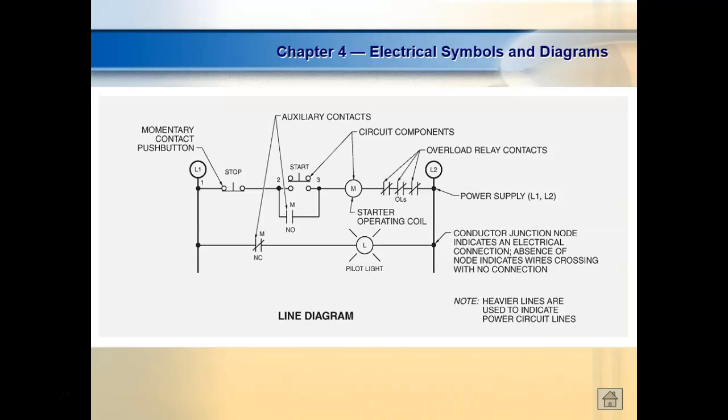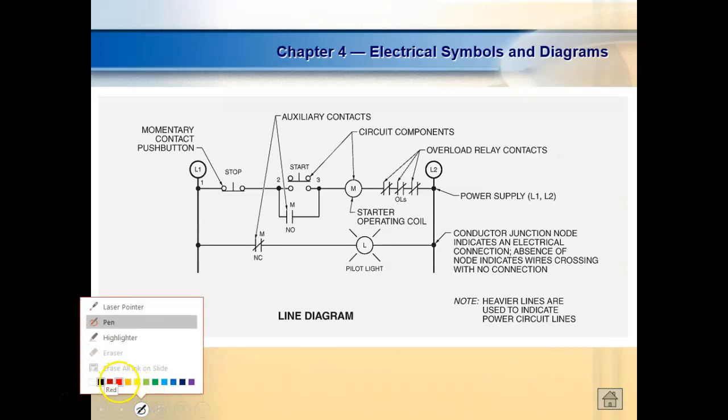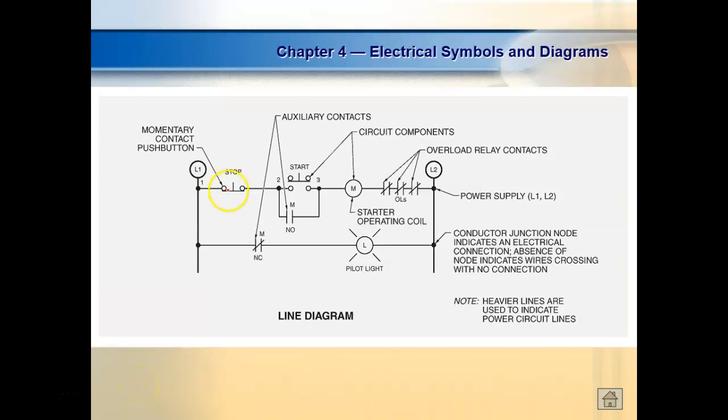So what happens is we come over here, and I think I told y'all, this is the most common circuit used in electrical controls. We have a normally closed stop button. We have a normally open start button. And so what happens is we have our voltage sitting right there. Nothing's going to drop any voltage, right, because there's no resistance there, no current flow.